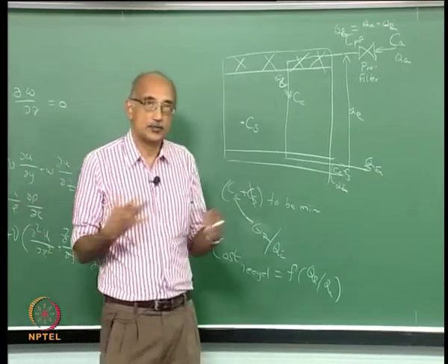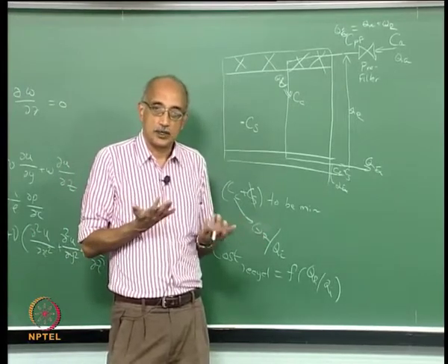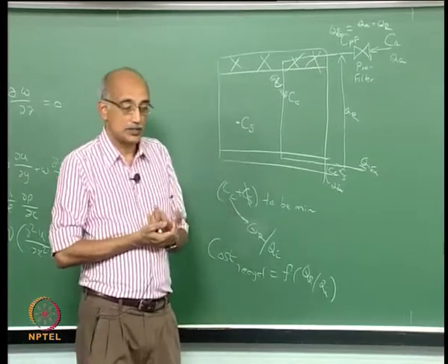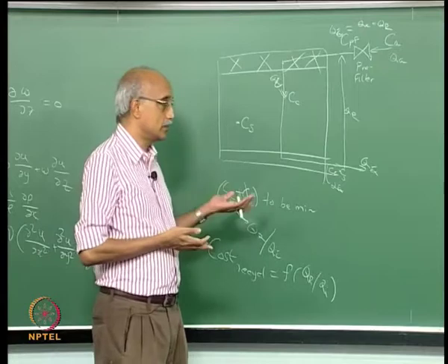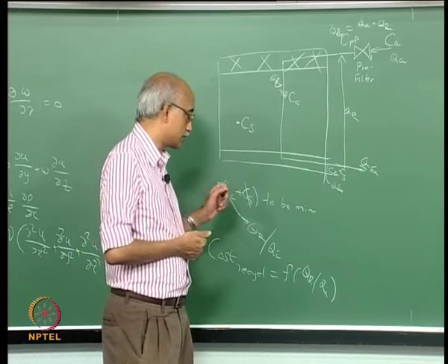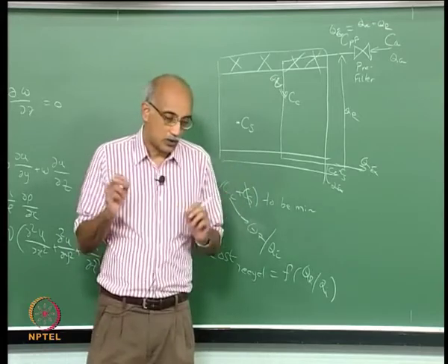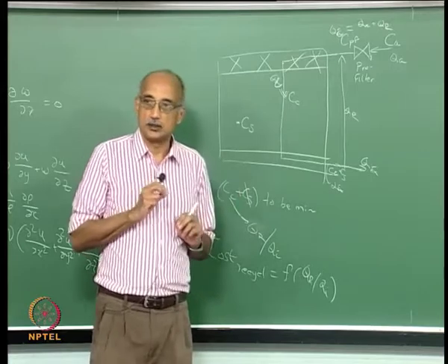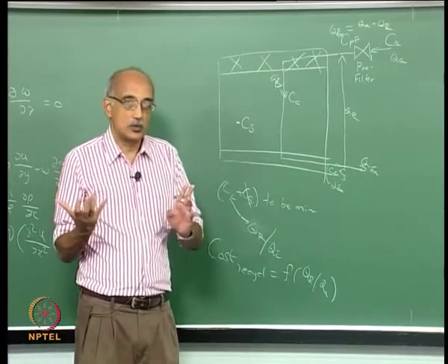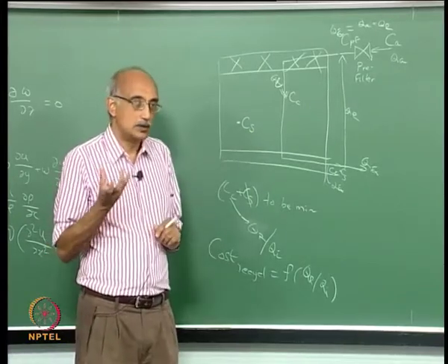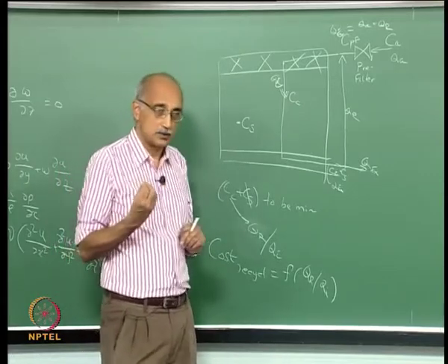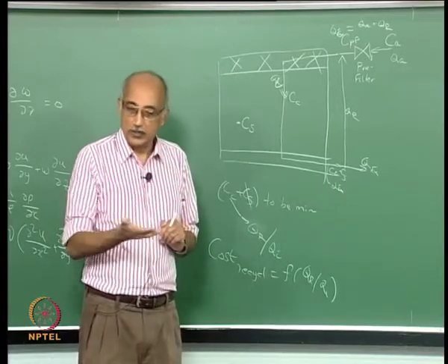No manufacturer has infinite resources at their disposal, so they are constantly doing this juggling to see what is achievable versus what is desirable given the process economics and so on. Now this also indicates that, as I've said before, if you cannot measure something, you cannot control it. I mean the assumption here is we know what these values are, but how do you quantify Cs, how do you quantify Cc? So you need good equipment and instrumentation to be able to measure particles in the clean room air as well as on clean room surfaces.